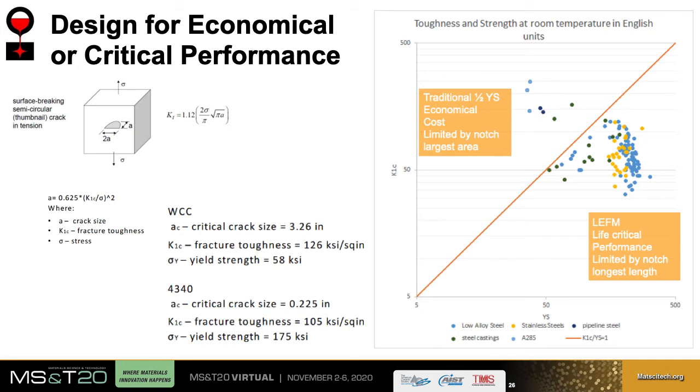To push us towards a more quantitative NDT, we need to have test data for steel castings with indications. We will develop a methodology that would allow designers to assess if the steel grade would behave in a ductile manner or a brittle manner. We are using fracture mechanics to look into the relationship between NDT indications and performance. Fracture mechanics approach using K1C value allows evaluation of how a material with a certain indication size would behave under an applied load. K1C is fracture toughness, or the value that represents the material's resistance against crack propagation.